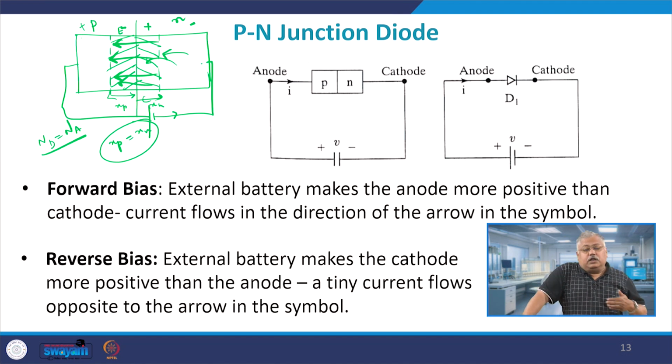But for an electron to move from the n side to the p side, it has to cross a voltage barrier or an energy barrier. Who gives this? This electric field. And who helps you to overcome this? The external potential bias. This external bias, this V voltage, is trying to overcome this barrier here, and it tries to move ahead. Once it does, the depletion region in forward bias reduces and the current increases. That is what has been taught to you in your basic device course.